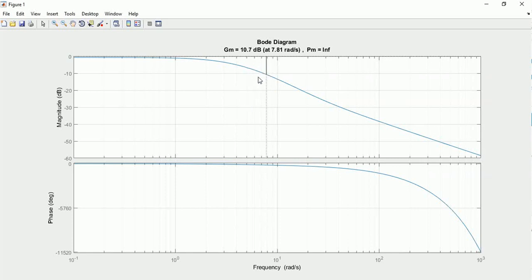So selecting complex poles that allow that will be good to mitigate the noise and not to spoil too much the gain margin. If we can do that, then the filter could be used, and then we can proceed with the PID controller.